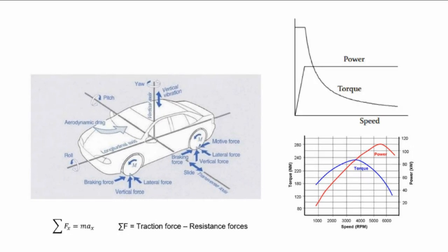model. What are the steps? Firstly, you will design the vehicle dynamics. Also, you will calculate your power demand, torque demand, speed demand, etc. You will add a drive cycle for speed variation, for example, the NEDC drive cycle, and then, as you did before, you build a DC motor model. You will connect the driver model, vehicle model, and your DC motor model. Also, you will add the battery model.